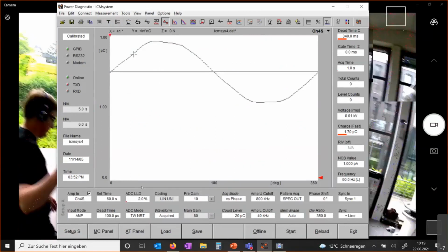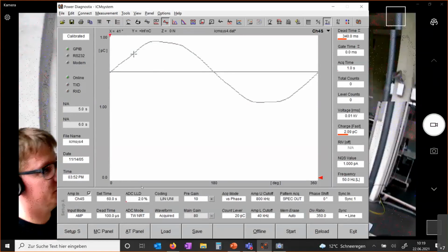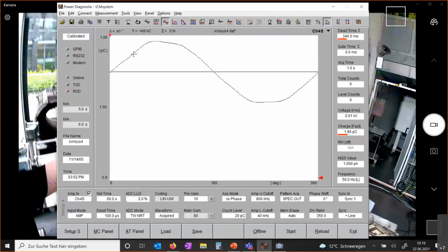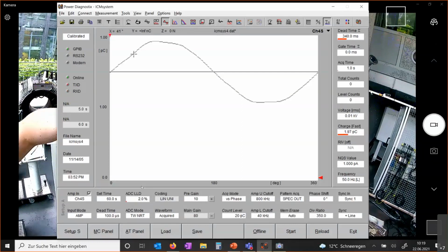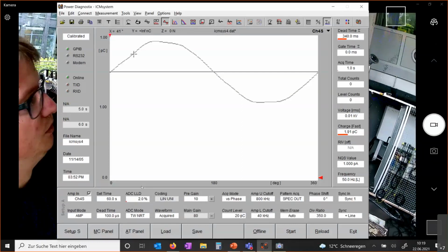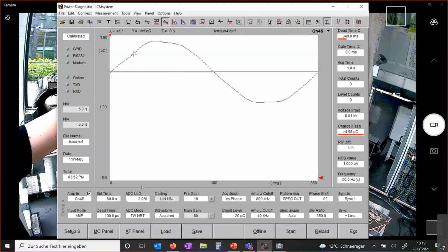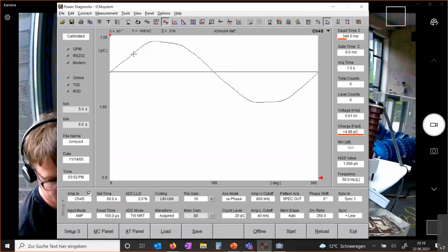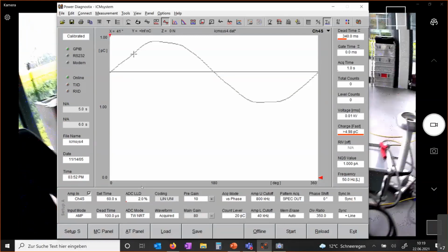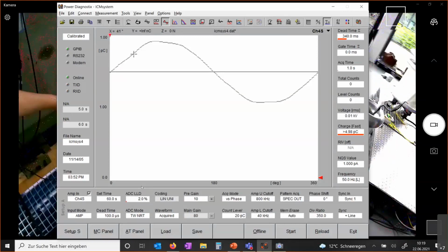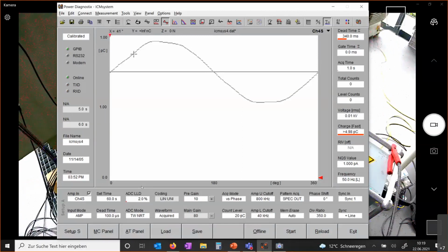René, can you follow me real quickly? So you can see here, this here is the low voltage side, which is completely shorted and connected via this cable to the HFCT, which I will show you in a second. So I will just clamp on the calibrator here. And you can see the HFCT down there. I created a little loop.